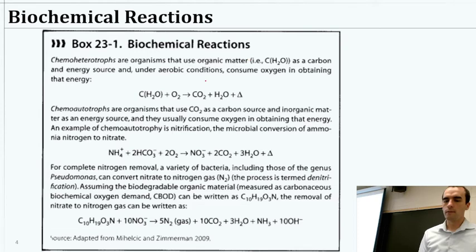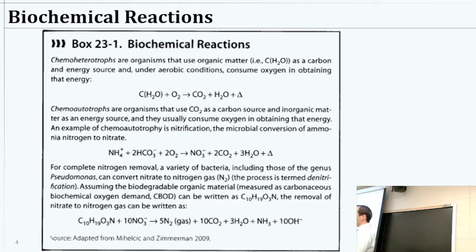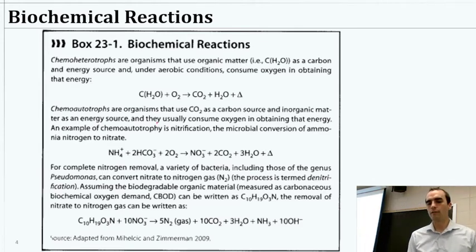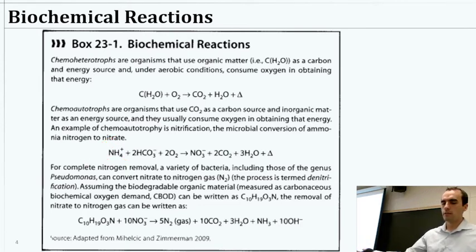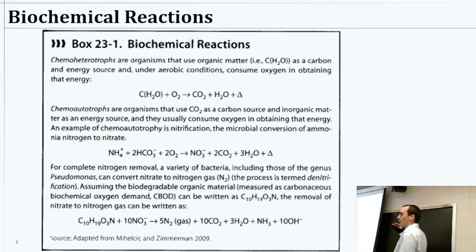So we've got those organisms as well, and that's really nice because one of the main concerns in any wastewater treatment is what happens to the ammonia. So if we don't have anything that's taking care of ammonia, then that's discharged downstream, and ammonia is toxic. So we don't want to leave that to the downstream organisms to deal with, because we're trying to protect whatever is downstream, right? That's the point of the wastewater treatment.